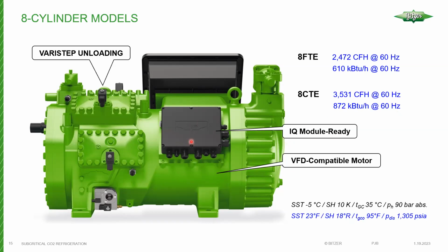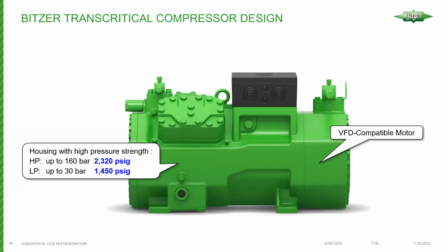So IQ module ready, meaning that you have a module that can control all of the peripheral accessories on the compressor. That includes unloading, oil safeties, crankcase heater. The module knows when the compressor is running or not, so it knows when to bring the heater on, and so forth. So it greatly simplifies wiring, just as it does with the HFC compressors.